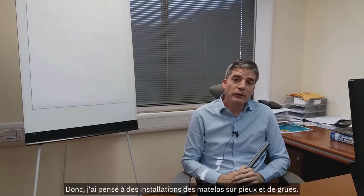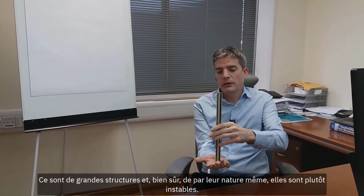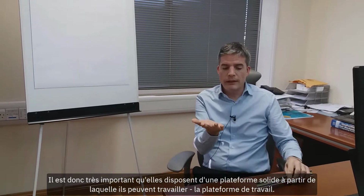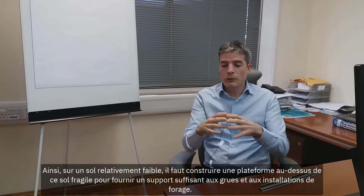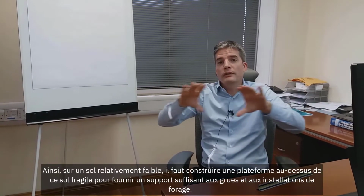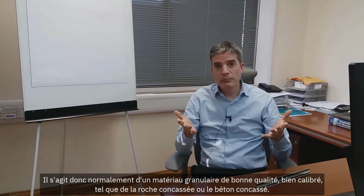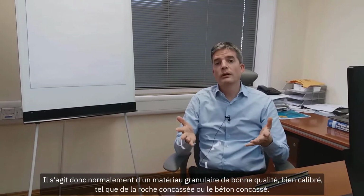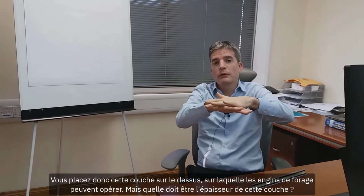So I was thinking about piling rigs and cranes. They are tall structures and of course by their very nature are rather unstable. So it's very important that they have a strong platform from which to work, a working platform. On ground that is relatively weak, you need to construct a platform over that weak ground to provide sufficient support to cranes and piling rigs. That's normally composed of a good quality, well-graded granular material such as a crushed rock or crushed concrete. So you place that layer on the top on which the piling rigs and cranes can operate.